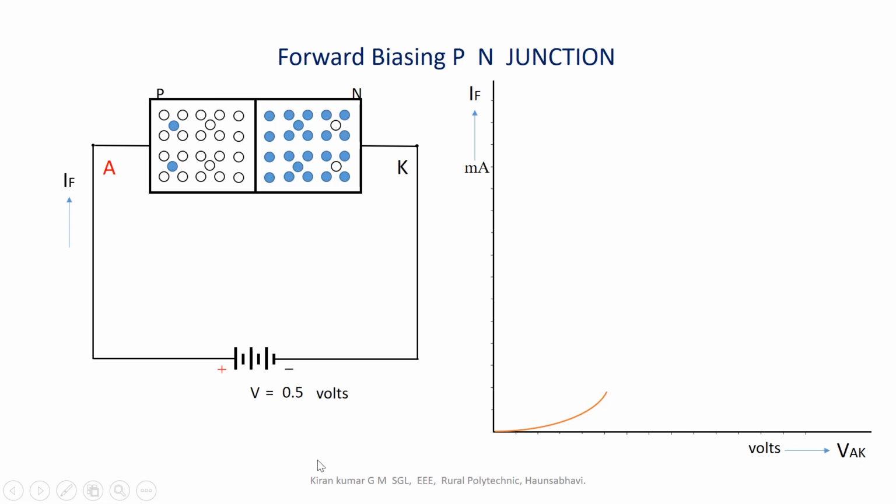When the barrier potential is reduced to zero level, there will be no opposition to the flow of charge carriers at this junction, meaning the resistance is brought down to zero value, and the diode is acting like a very good conductor. With no opposition to the flow of any charge carriers, it acts as a very good conductor here.